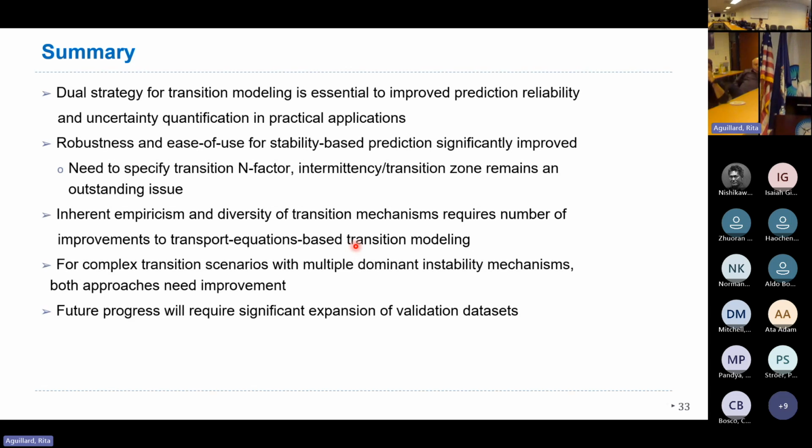No, for the PDE-based method it's not repeating, but for the stability-based method it's essentially reverse, right? It's usually maybe 3x because you're doing 3 times the iterations, but the turbulence cost itself is quite small. A lot of the cost comes from building the profiles for 3D cases. For a structured grid, it's cheaper. For unstructured, extracting the boundary layer profiles is a little more expensive. So that is one of the pieces which has been looked into.